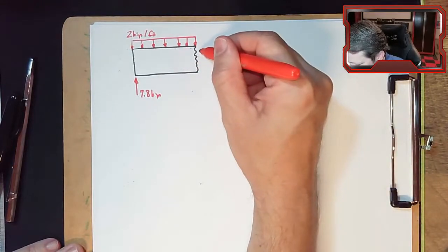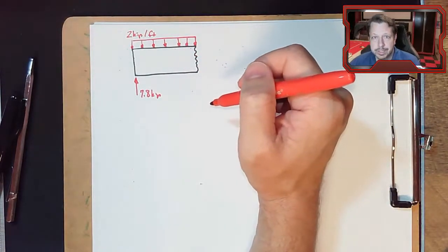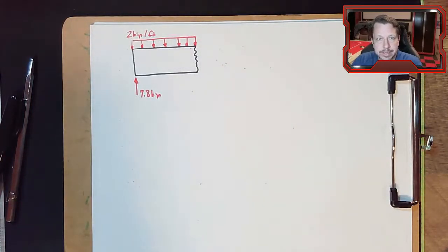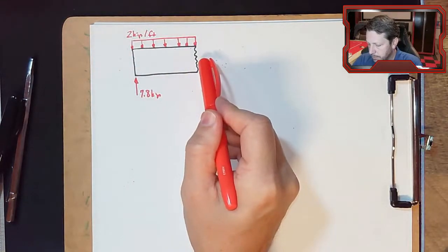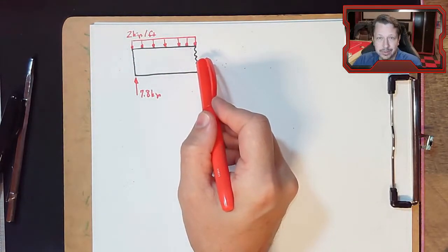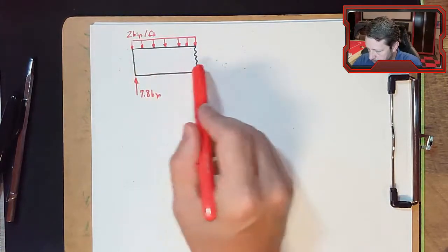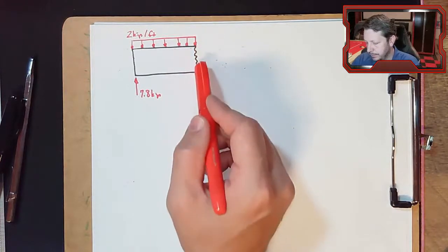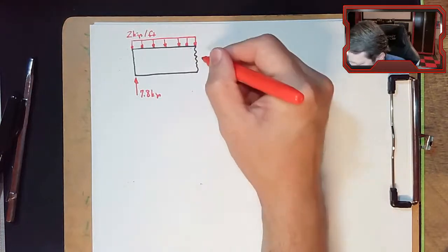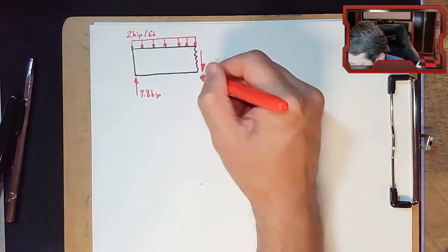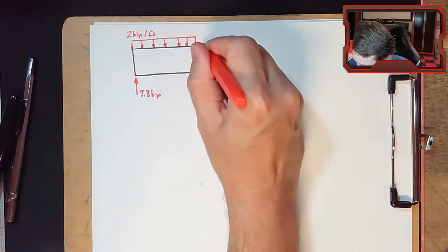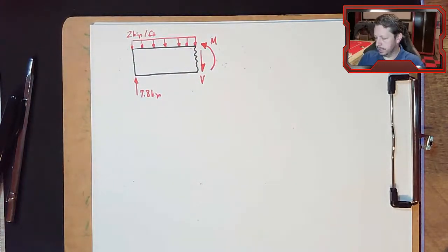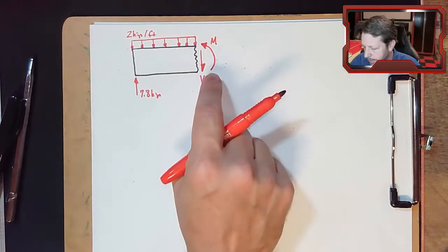We do have to remember which direction to draw these internal forces. So most of the time I tell you just draw them in the positive direction, or draw it in tension, you know, whatever. These we have to be more specific with, so that things later on will work out. So when you draw a beam and you draw a free body diagram where you've cut the right end of that free body diagram, you put the shear force as positive downwards and the internal bending moment as positive counterclockwise. You don't have to write your equations that way. You have to draw the arrows that way.